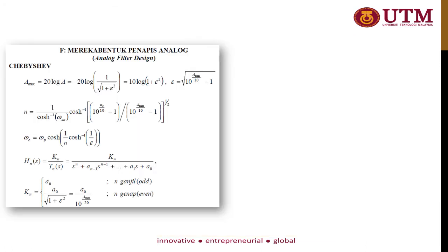Okay, the most important part in this chapter, you need to refer to lots of appendices, and it depends on the type of filter you'll be designing. For example, if you notice that the filter response has a ripple in the passband area, you know it belongs to Chebyshev. So you need to refer to all equations from Chebyshev.